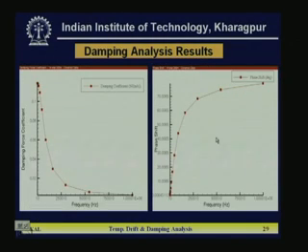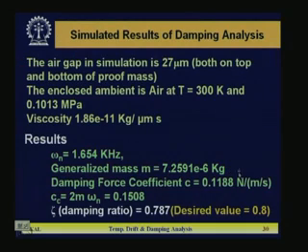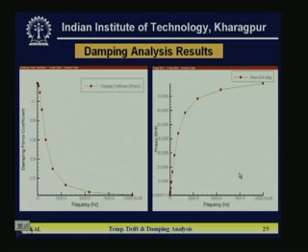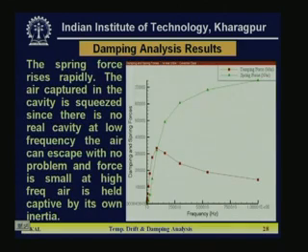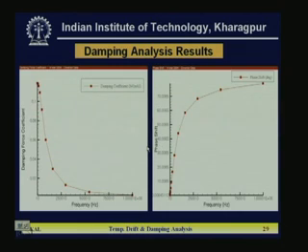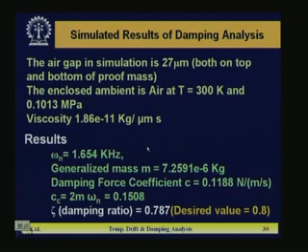Now, here the damping force coefficient and the phase shift of the damping have been plotted. This is the force coefficient and the phase, and here also we found that the variation at low frequency is steep and the high frequency variation is not that much. And in the earlier diagram you can see there is a point where both the spring and damping force are the same, a crossover point, and we have to take that particular point, at which frequency it is the same, and accordingly the omega n value is decided, and you can calculate the damping factors in both the cases.